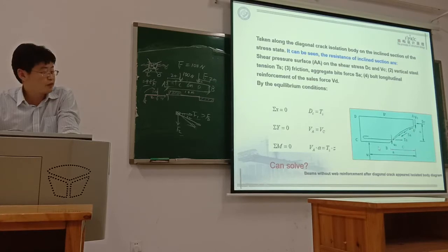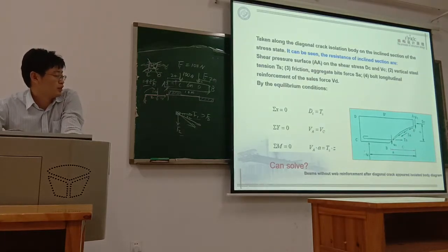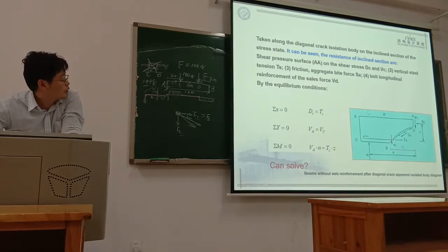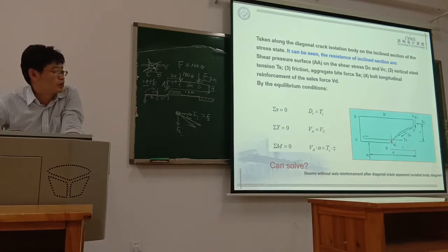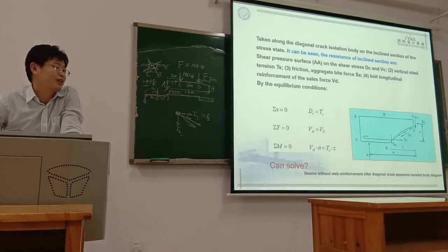The main force we consider is the tensile force, and also the compression force and the shear force at this position. Also, the reinforcement can bear some part of the shear force, the dowel force of the longitudinal reinforcement VD. This VD is also not so large compared to the shear force here, and it is difficult to get the exact value.